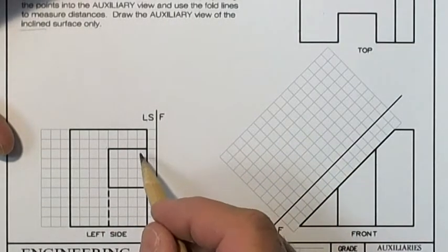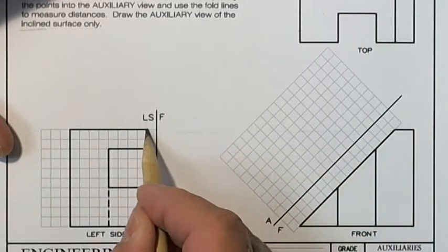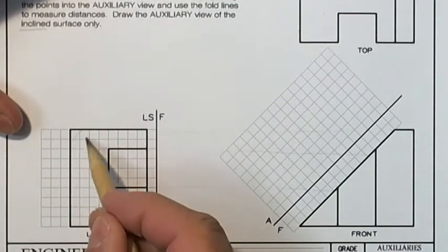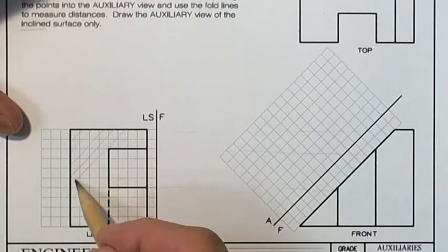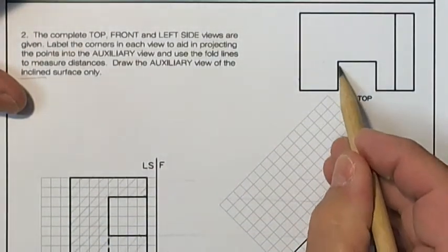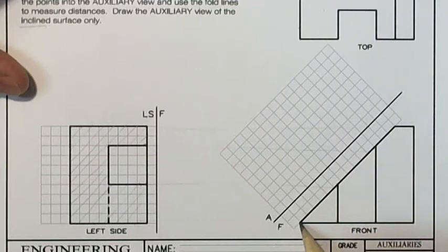And as I look across here, I can see that as I project over here, my corners match up. The hidden line is the back side of this edge here, and therefore very lightly, just to give you a sense of where it occurs, this is my inclined surface here. This is the notch or the opening. If I move back to the top, I can see that notch or that opening. So my inclined surface goes from here down to here.